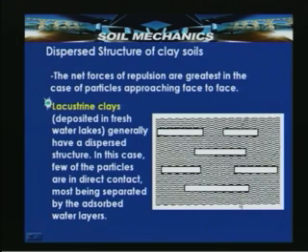This type of deposit is possible for lacustrine clays, that is, clays deposited in freshwater lakes, which generally have a dispersed structure. In this case, few of the particles are in direct contact, most being separated by the adsorbed water layers.